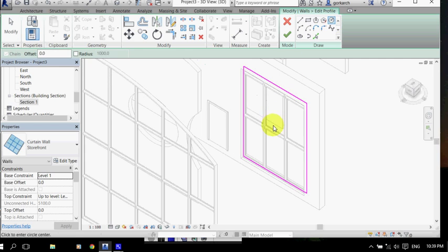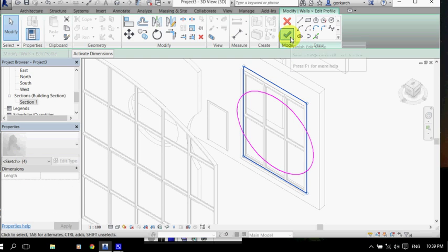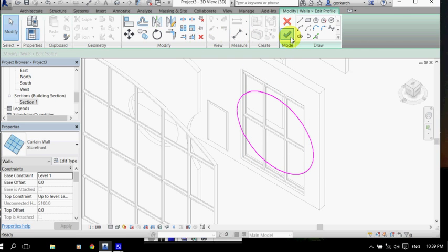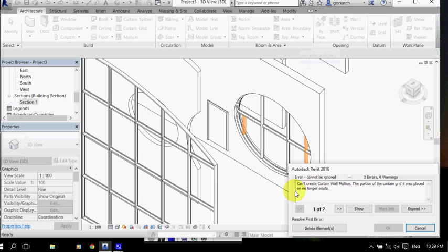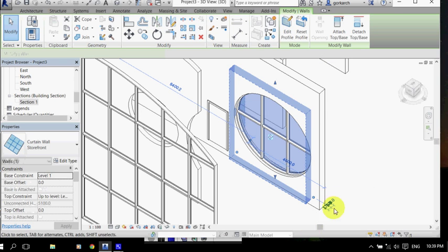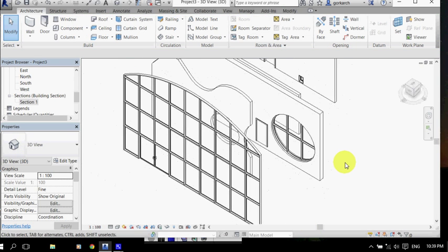So you can do some fancy shape. I'll go circle somewhere in the center here, escape, escape, and I will delete the squarish shape. So tab selects all connected elements, left click, delete, and finish. Delete redundant elements, and you have a nice design.